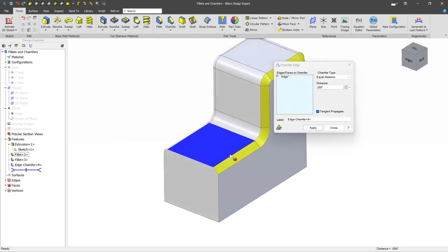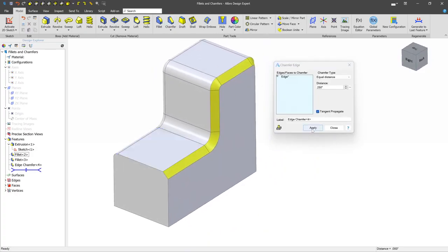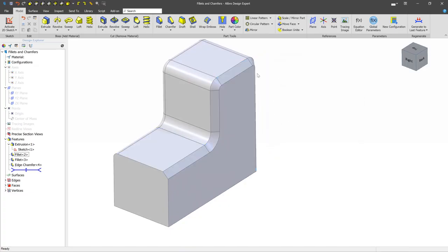It's also a good idea not to try to do too many things in one particular fillet or a particular chamfer. So if you have 75 inputs to one particular fillet, that's going to potentially cause problems for a few reasons, but least of which is going to be editing it. So try to keep things as simple as you can, break them up into logical groups, and try to place them, generally speaking, towards the end of your design.